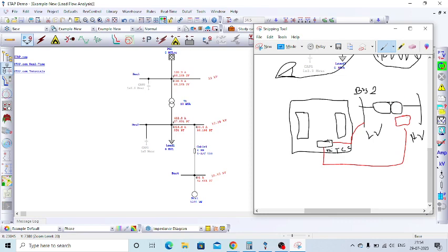In the primary winding, the OLTC will be there. So the RTCC will give the control to this tap changer which is in this transformer. It will change the tap, so that the LV bus voltage can be improved. Okay, I think everyone is clear on this one.